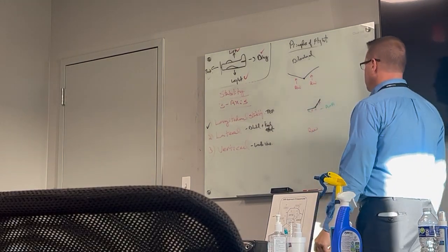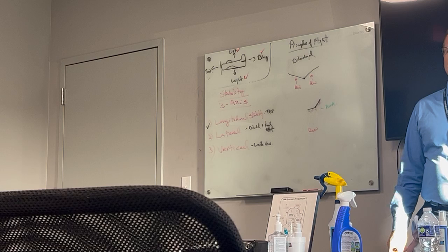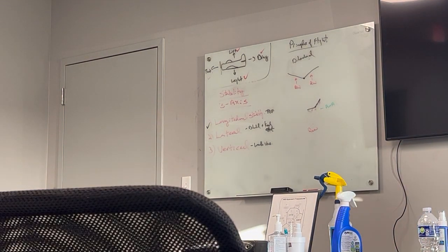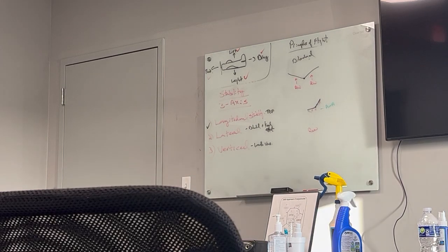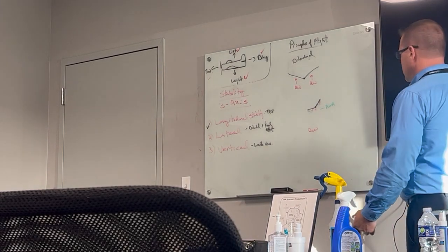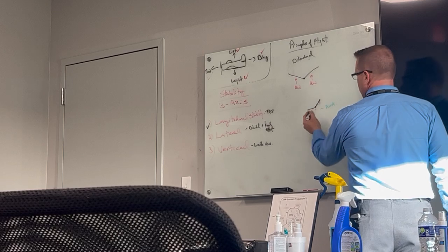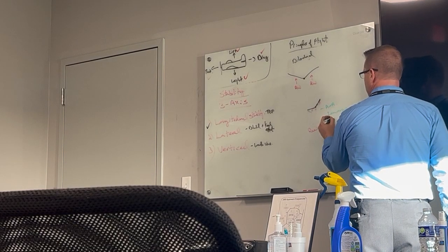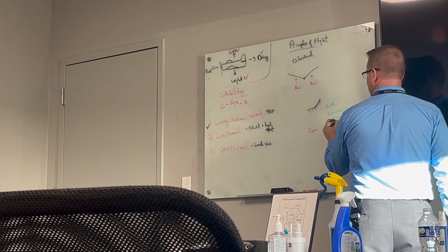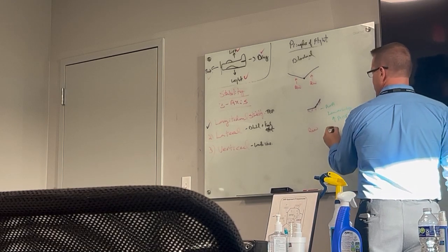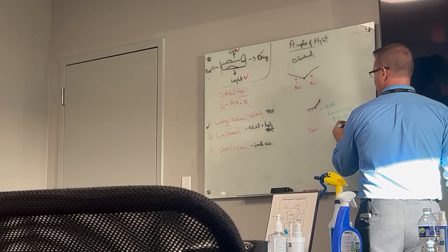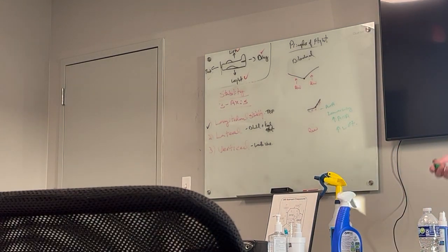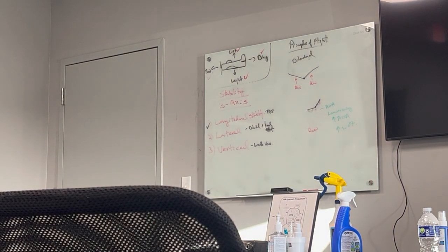Those green lines represent the angle of attack because of that dihedral that's built into the wing, that occurs when we go into the side slip condition when the aircraft is disturbed. So what happens is, on the lower wing, we end up with a greater angle of attack, which means we have increased lift on that wing. And therefore the plane will have a tendency to right itself based on that fact alone.